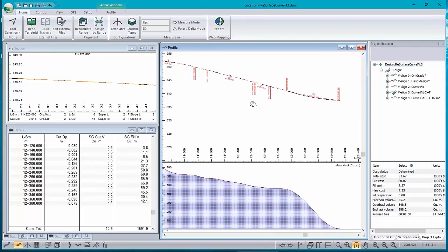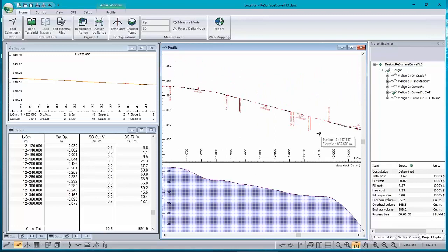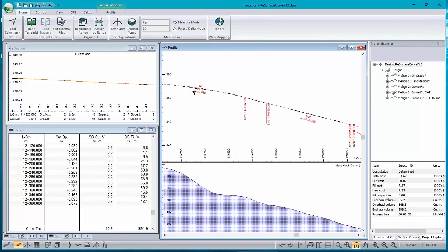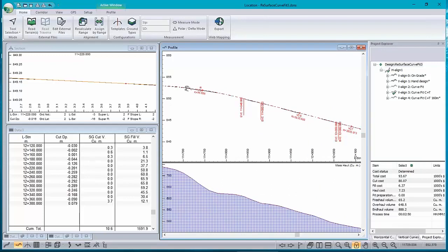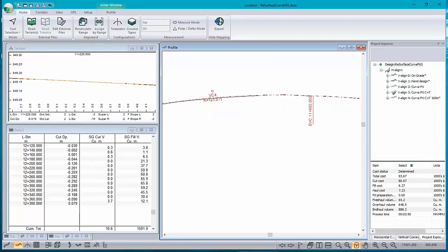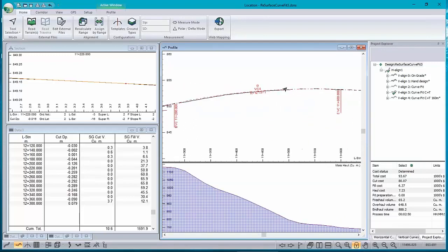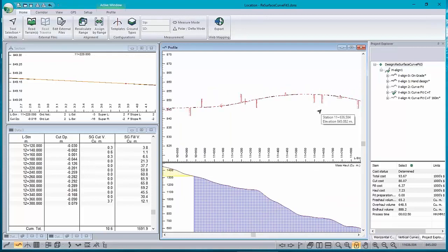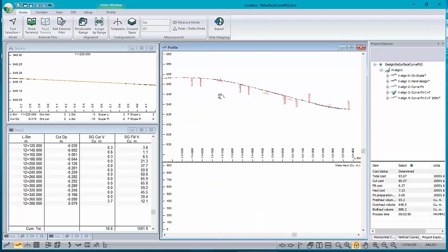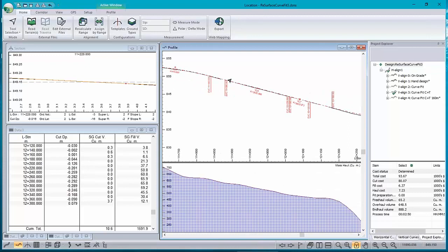So the optimizer is just an algorithm. It's come up with some reasonable curve K value here, 95 there, 121 there. So that curve is actually not a continuous grade, right? That's why it's hard to match when you're doing it manually. And then it put in these really, really long curves here, which are essentially tangents.